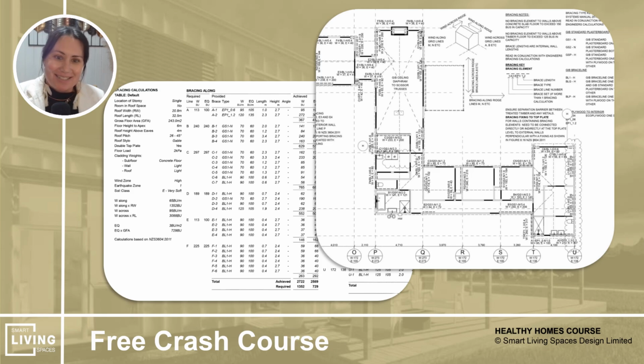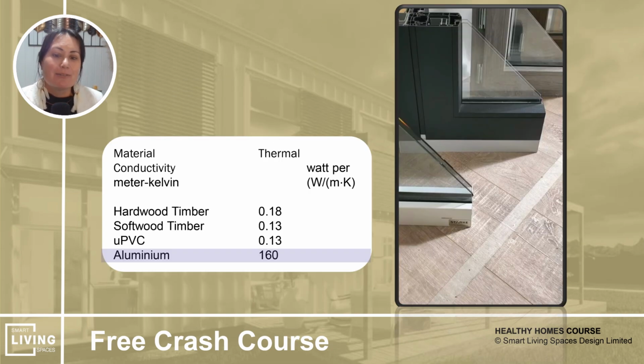Okay, double glazing in windows. Now, double glazing is good, but your existing windows, particularly if you've got old timber windows, might not be able to take the weight of the glazing unit. So you do need to consider your options. Because you want to make the right decision to get maximum benefit out of your home improvements, right? In some cases, you will need to rebuild part of the window.